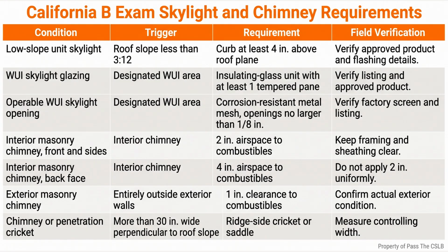I think of sealant as support, not a substitute for drainage. Water should be directed around the opening by the roof assembly. I coordinate the framer, roofer, and skylight installer before concealment, because each trade controls part of the same water path.